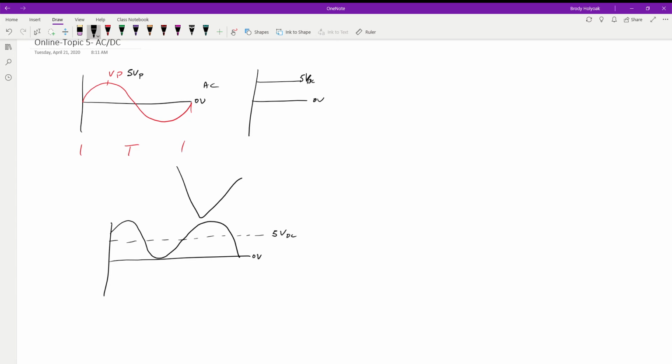And so what we have is a plus and minus 5 volts over top and underneath of this 5-volt DC signal. So now when we do that, we're going to have a max value of 10 volts peak, and a minimum value of 0 volts. So we're still maintaining our 10 volt peak-to-peak signal. We're still maintaining our 5-volt peak signal, but now we've just shifted it from 0 up to 5 volts.